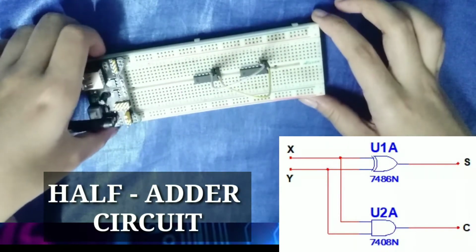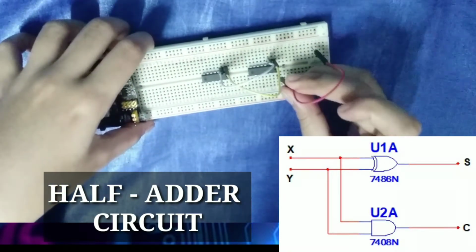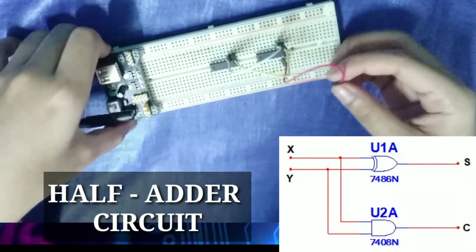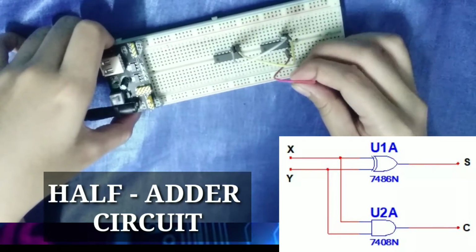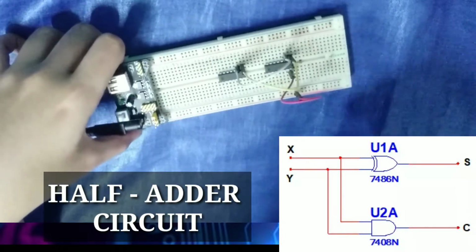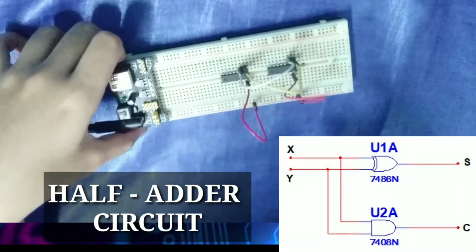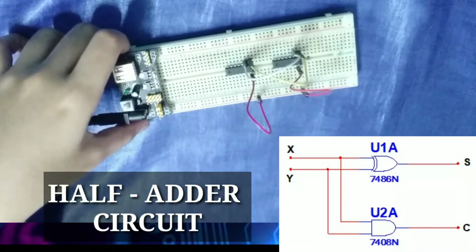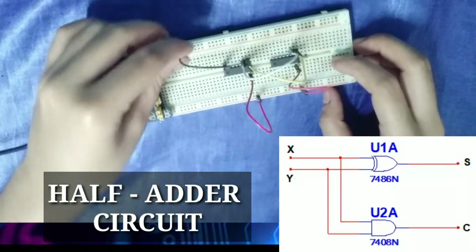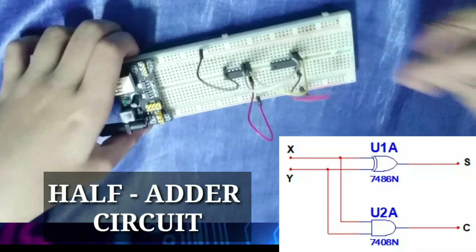And for our VCC connection, do not forget that this pin here on the other side will be the connection to the VCC or the voltage supply. This is important for both of the ICs here. And also, don't forget to ground the components on the 7th pin of both of the integrated circuits. Okay, let's just ground the components.